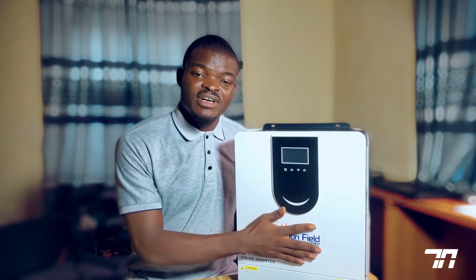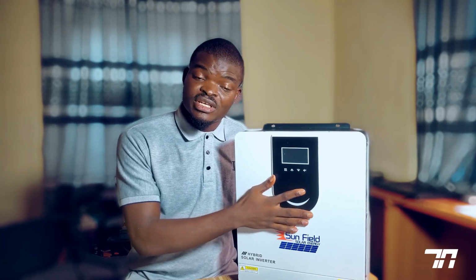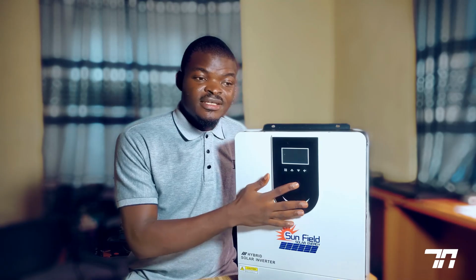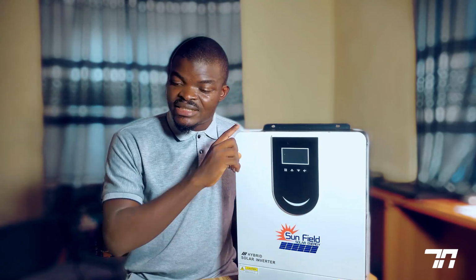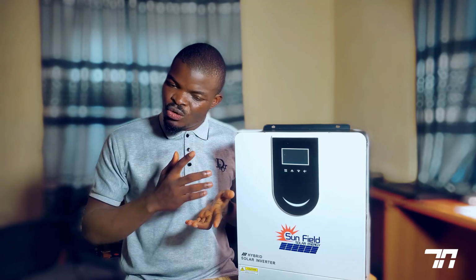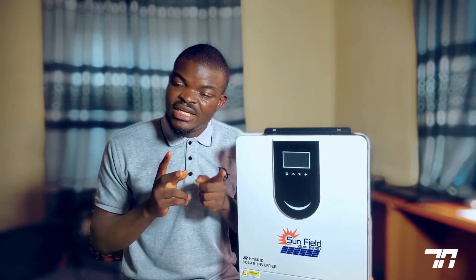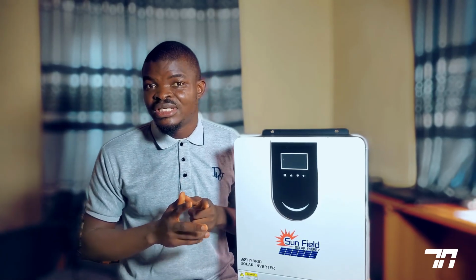strings for this inverter, a 16 pieces of solar panel, 300 watts. Then I can connect eight pieces in series. So each of that 8 pieces I can use as low as 4 mm cable to draw those strings individually, making it 4 cables.